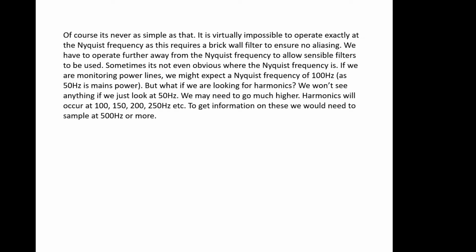So just a few words of warning there. It's never quite as simple as operating at Nyquist. It becomes virtually impossible to operate exactly at the Nyquist frequency. Never say never though, because this requires a brick wall filter to ensure no aliasing.